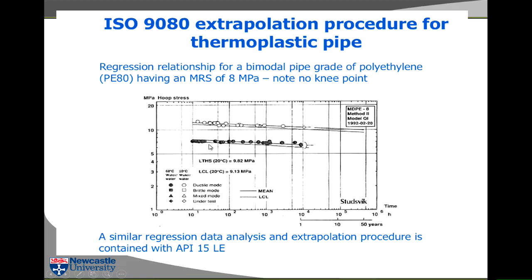And this is a bit misleading, actually, but this is at 60 degrees C, but we should have another curve at 80 degrees C. There'll be another curve at 80 degrees C running up to 10,000 hours, and that must show no sign of a transition. Like I say, if there is no transition there, it doesn't mean that the transition is never going to happen. It just means that if you consider the temperature change, the time change with relation to temperature of the knee point, that will simply tell you that there is no transition going to happen within the design life of the pipe.